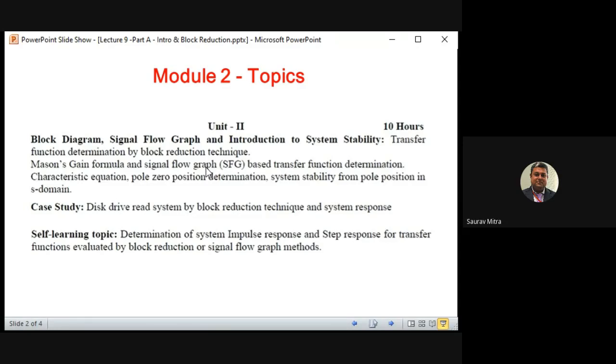So whatever X(s), Y(s)/X(s), transfer functions we have found, we have to take X(s) as delta(s), that is, the impulse signal. When we give it, we have to find out what Y(s) is. So Y(s) is equal to delta(s) into T(s). From there find y(t). So when an impulse signal is given to the system, whatever the system output is, that is called the impulse response of the system.